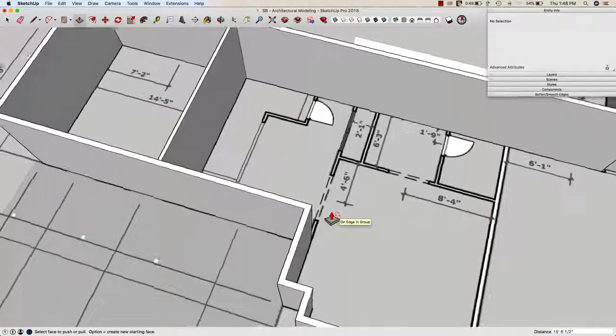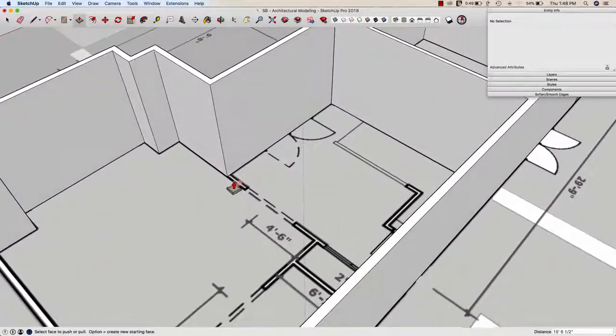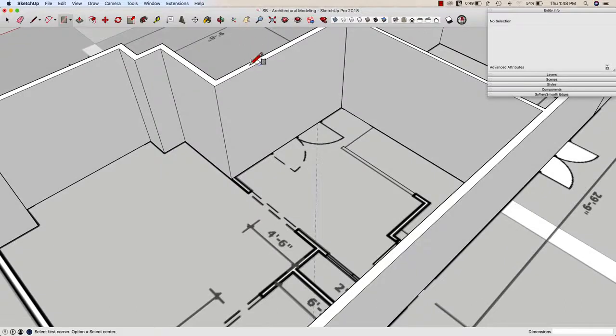All right, as I keep working my way along here I have a 3.5 interior wall that lines up with my exterior. So I'll do the same thing I did before with my rectangle. I'll click here. I'll drag it up like this. In this case, I don't have that snap point to pull across because it's the wrong size. But I can type in 3.5 comma 9 feet, and that'll give me that rectangle. I can push-pull,